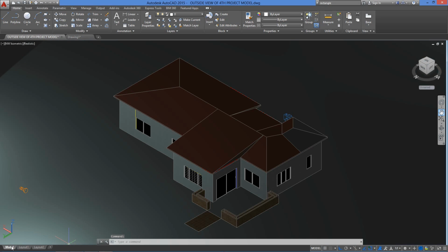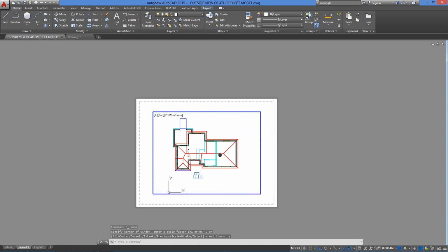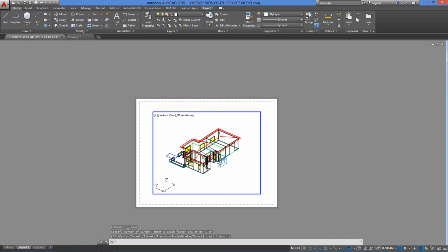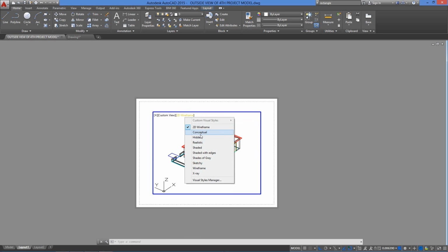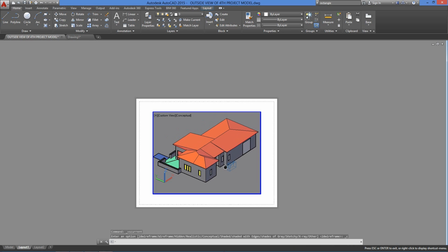On the other hand, on the left, we have these 3 tabs. The current one is the model space, but the other 2 saying layout are considered paper space. Click one of them and this is what we have. This resembles a sheet of paper and is basically a window to look into the model space. It's in here where we scale our drawing and decide how to present it to the clients.